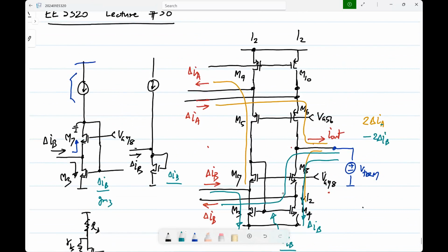Okay. So the point is whether you inject the currents differentially to these nodes. This was more intuitive in that way. These were just common gate amplifiers for the differential pair. But you can connect them to these nodes also, and it works in exactly the same way. So you can connect them either there, which is a more natural sort of cascode-like thing, or here into the current mirror nodes. It works in the same way. Okay. Any questions?